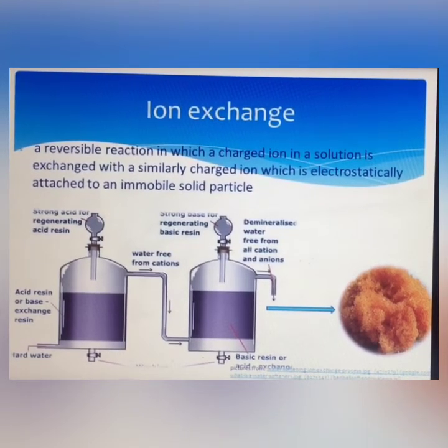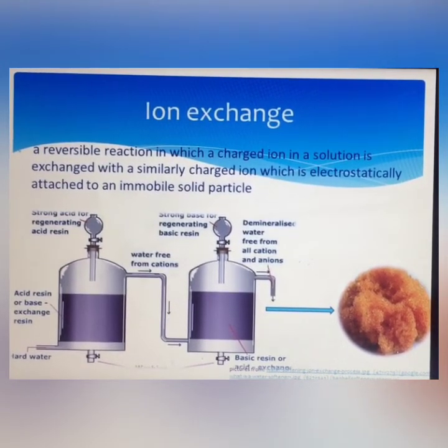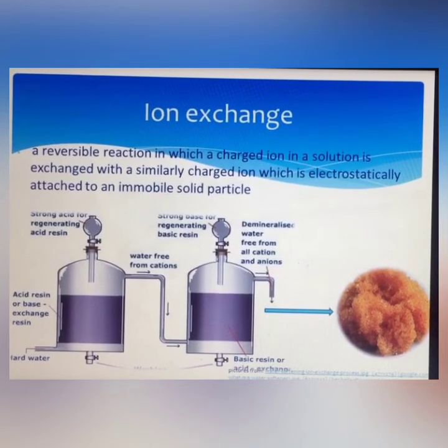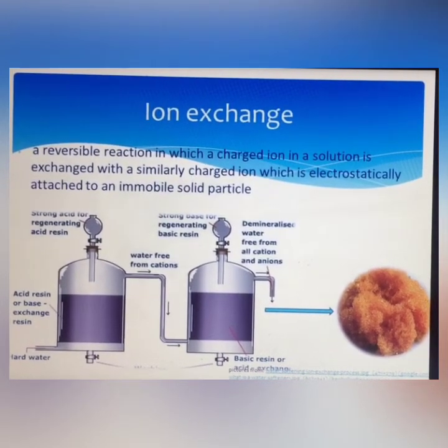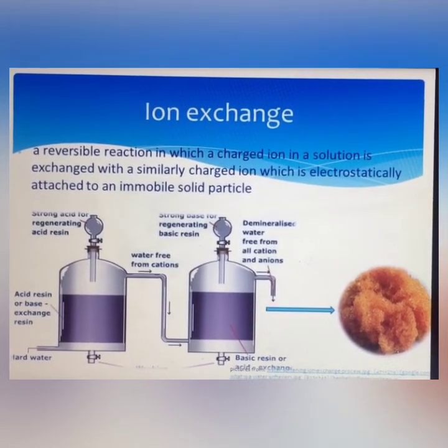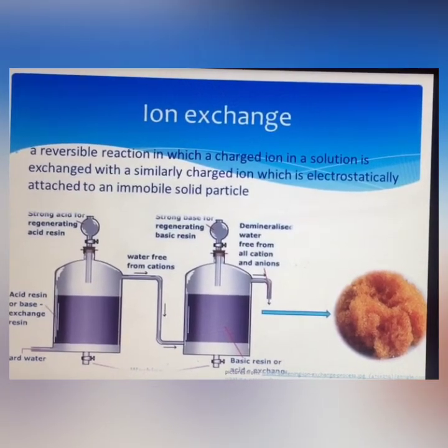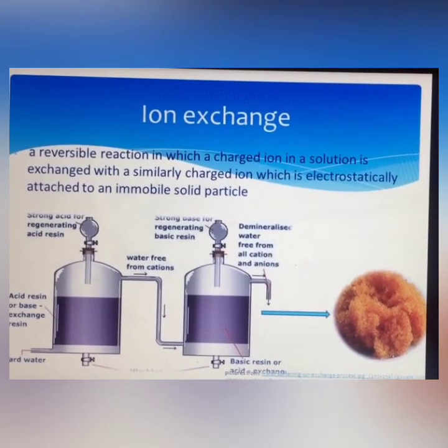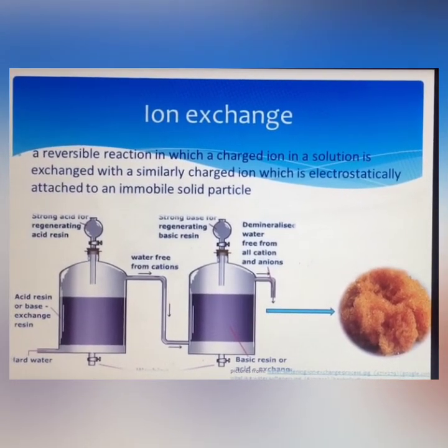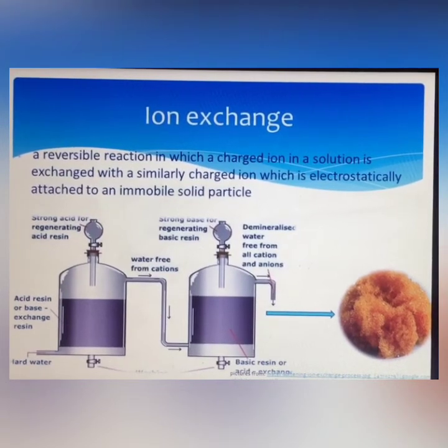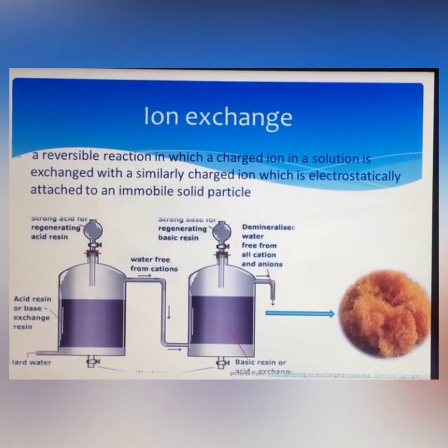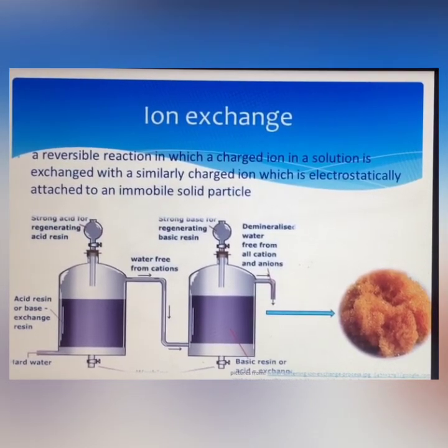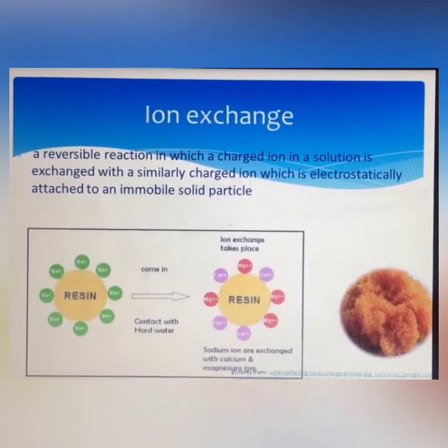Polyvalent cations are exchanged with sodium. The wastewater is introduced to a bed of resin. In the solution, the sodium is exchanged with the cations. The water is also introduced to a basic resin to remove the anions in the water.